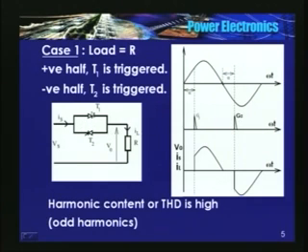When T1 is triggered, input voltage Vs is equal to output voltage. Load is purely resistive. Current and voltage are in phase. So the waveform of source current, which is equal to the load current, is same as V0 itself.